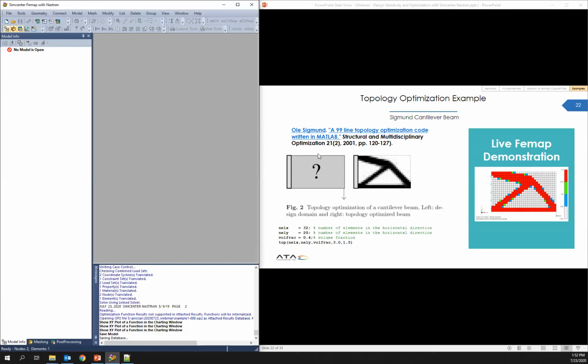You explore with an optimizer what the efficient topologies are in this space. That's what topology optimization allows you to do, using a mesh that fills this domain. The optimizer will pick where the material is to satisfy the optimization criteria, which typically, for a case like this where you have a static case,